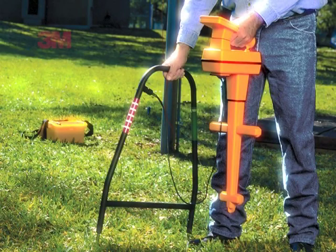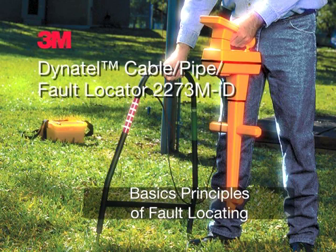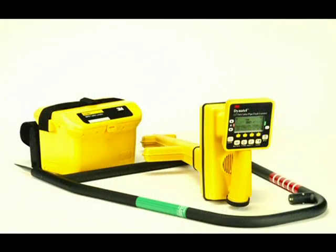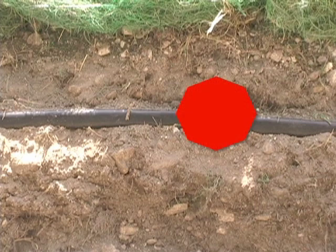This chapter will provide the basic principles and a guide to fault locating with the 3M Dynatel 2273 MID cable, pipe, and fault locator. The 2273 MID fault locator will find earth return faults. An earth return fault is one in which an insulated conductor is physically making contact to the dirt due to some damage that has occurred to the insulation of that conductor.